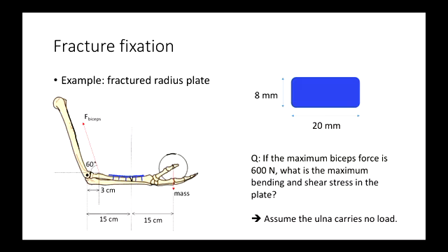Okay, so we have the mass, so we can substitute into here, and we get Ry equals negative 467.6 newtons. Okay, so we now know the forces. Now we can calculate the bending moment applied to this. We know that the load, as in stress, will be shared at these locations, whereas in this region here, all the load's going to go through that cross section.